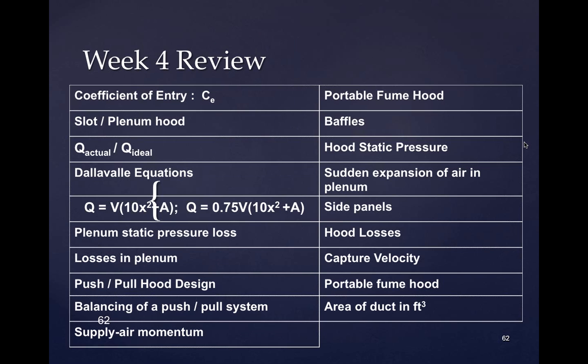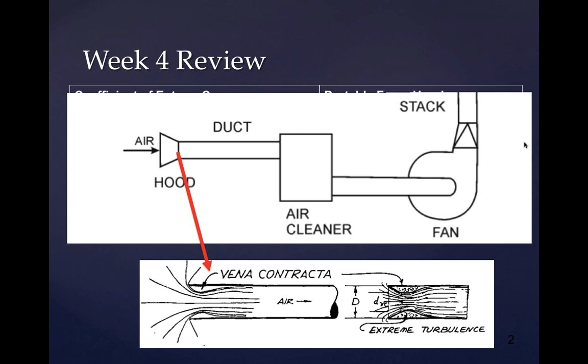If I have this room and a big exhaust, a hood and exhaust fan in a corner of this room, and I have all the windows closed, the door closed, and so forth, you're not going to be able to suck air out of this room. The hood's not going to work, right? You need to be able to pull air out of the room effectively in order for it to work.